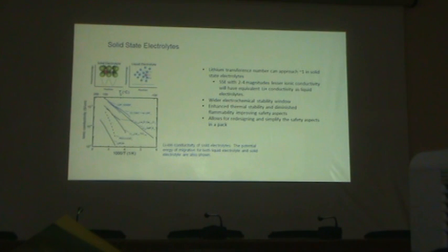And there is also the solid state polymer electrolyte, which is, for example, polyethylene oxide, PEO, with some conducting agents in it, some lithium salt in the solid state. That is different from the lithium polymer battery that is commercialized. The commercialized lithium polymer battery uses gel technology, that is a membrane with a liquid organic solvent. That should be known. And here the case is again similar: the separator function is also there for solid electrolytes.